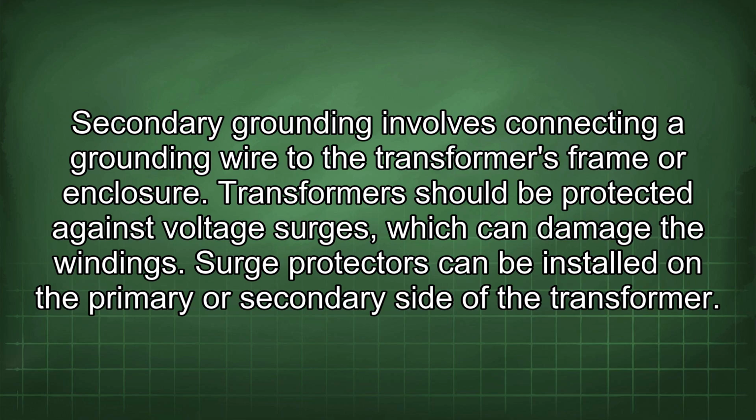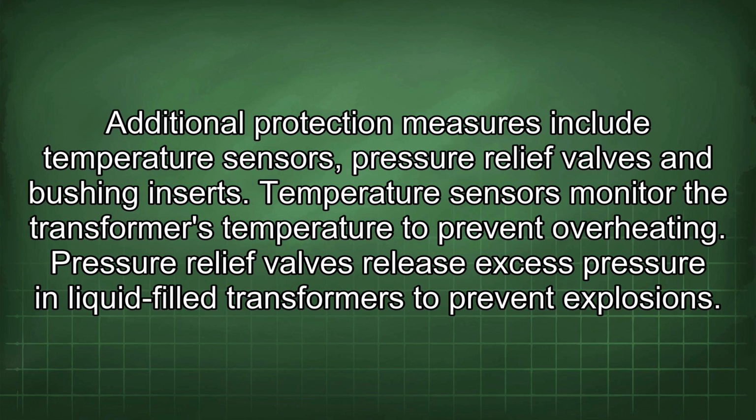Transformers should be protected against voltage surges, which can damage the windings. Surge protectors can be installed on the primary or secondary side of the transformer. Additional protection measures include temperature sensors, pressure relief valves, and bushing inserts.